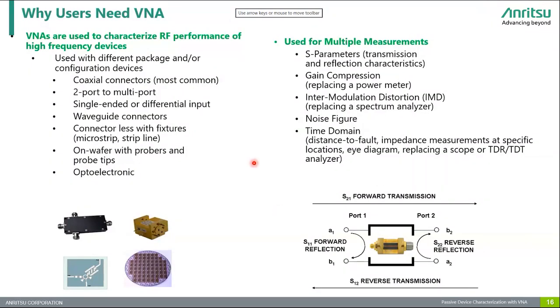On the hardware side, VNAs are compatible with a wide range of device configurations: coaxial connectors, which are the most common, waveguide interfaces, single-ended or differential inputs, connectorless setups with microstrip or stripline fixtures, and even on-wafer probing for semiconductor testing, as well as optoelectronic device characterization.